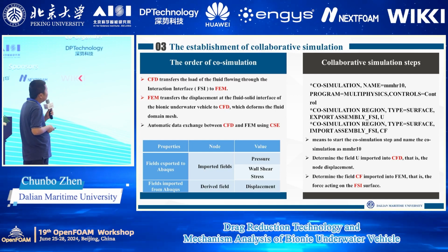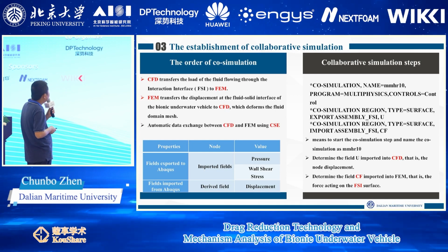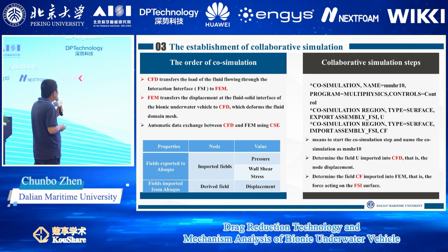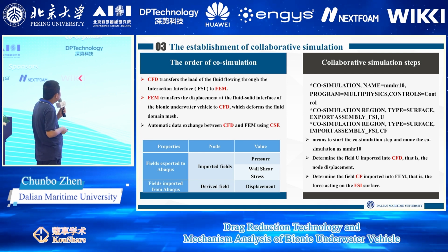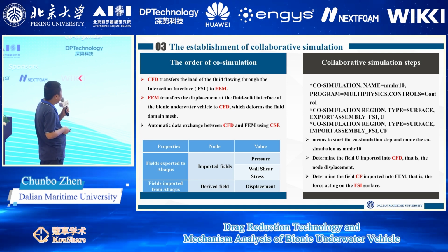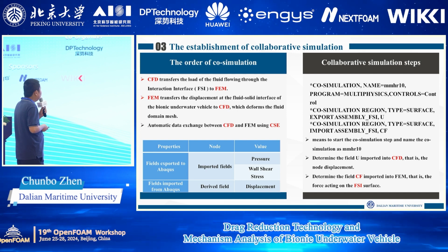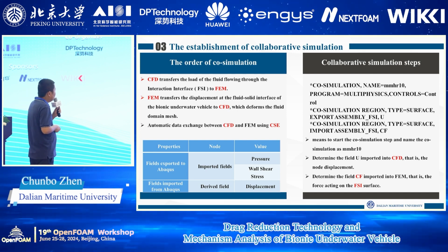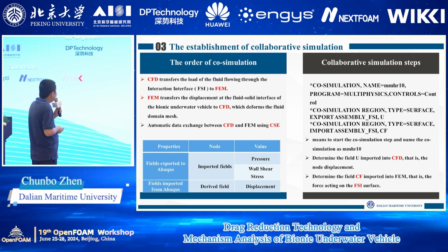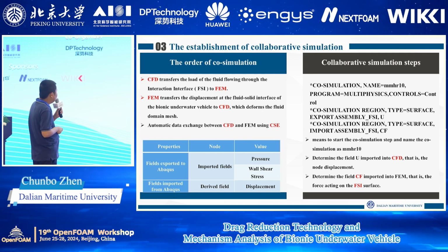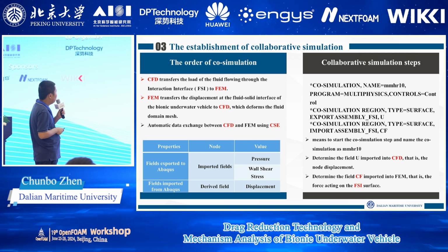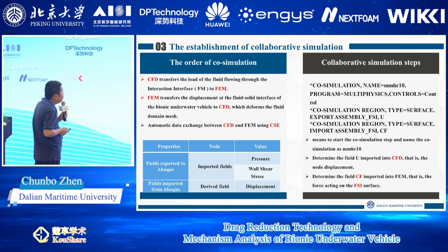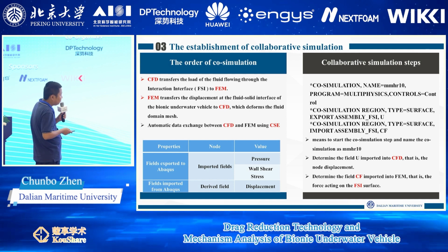This is the order of the co-simulation. First, CFD transfers the load of the fluid flowing through the interaction interface to FEM. FEM transfers the displacement at the fluid-solid interface of the bionic underwater vehicle to CFD, which updates the fluid domain mesh. Automatic data exchange between CFD and FEM uses CSE. This is the cooperative simulation step.